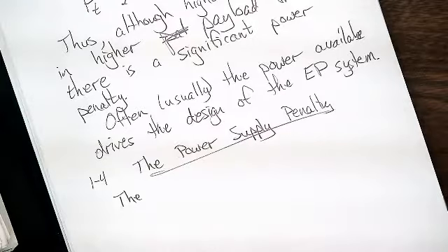A power processing unit conditions the electric power to the form needed by the thruster. And that conversion system itself has a mass and volume associated with it. If you were using a chemical rocket, you wouldn't have one of those power conditioning units. So this serves as a penalty on the EP side of things when you're doing comparisons of various thrusters for particular missions.